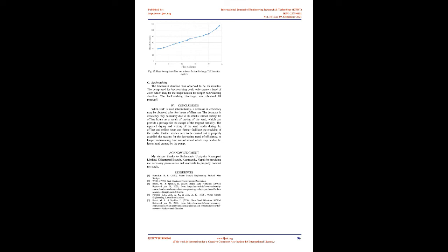For the discharge of 720 L/min, the plot of removal efficiency against filter run for the filter during the 3 cycles are shown in figures 3.4, 3.5, and 3.6 below. A similar trend of efficiency as that of the previous discharge was obtained in all the cycles. The peak was obtained at the first 4 to 5 hours of the filter run. Also, at this discharge, lower efficiency is observed at the end than that of the previous discharge. This is due to the greater solid loading at the greater discharge, which further enhances the escape of trapped turbidity.